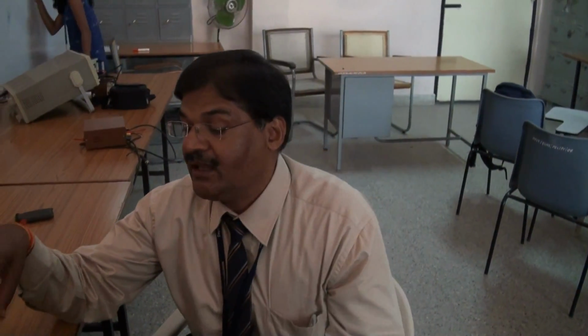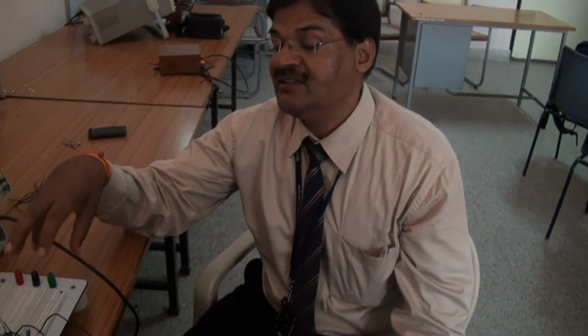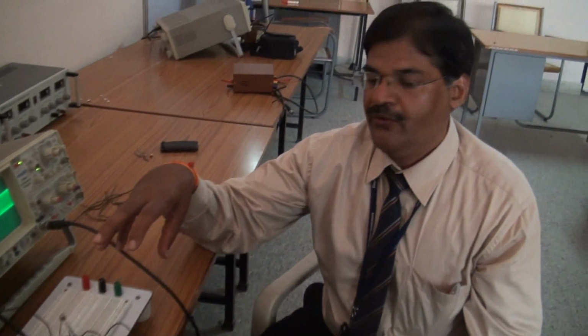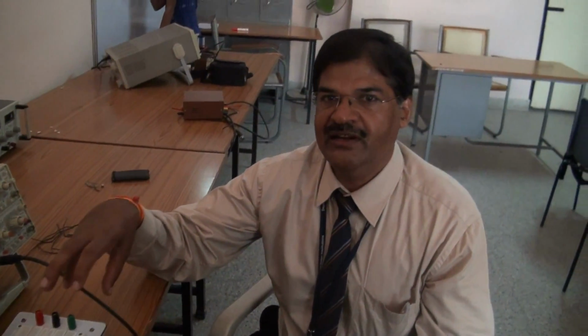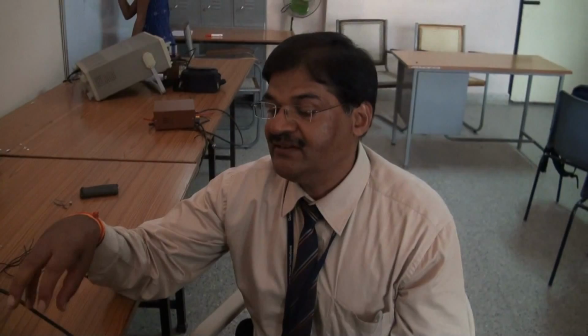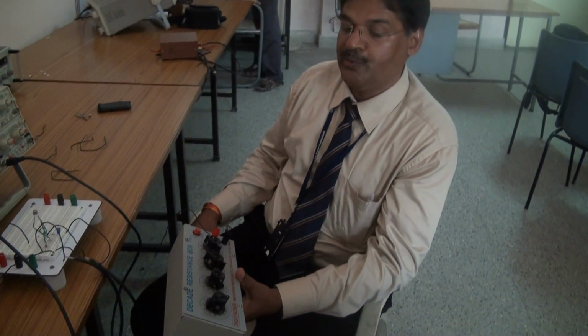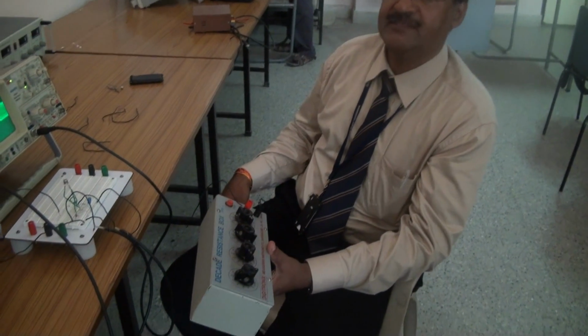The other name for this amplifier is RC coupled amplifier, because using R and C components we can make this circuit. Particularly the CE amplifier is a voltage amplifier. Wherever voltage amplification is required, we can use this amplifier. But this amplifier is not suitable for impedance matching purposes, because input impedance is not very high and output impedance is not very low. That is the reason it is not suitable for impedance matching, but it gives very good voltage gain. To measure input and output impedances, we need a decade resistance box.